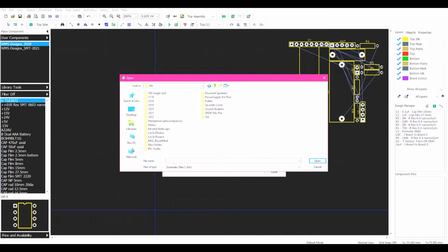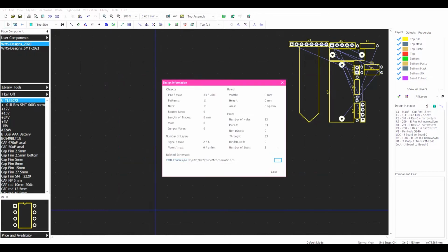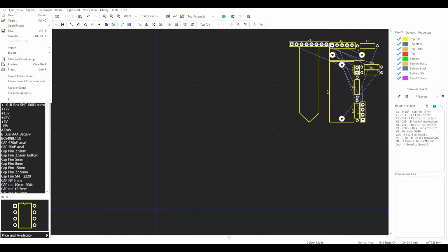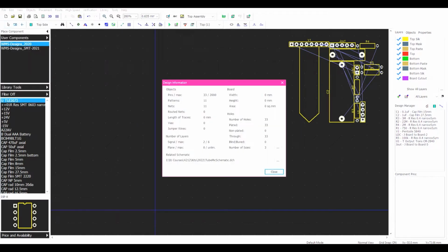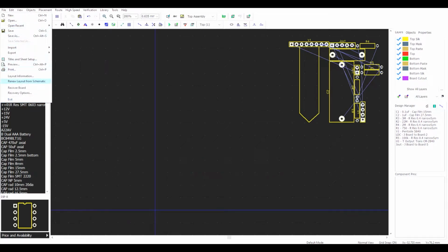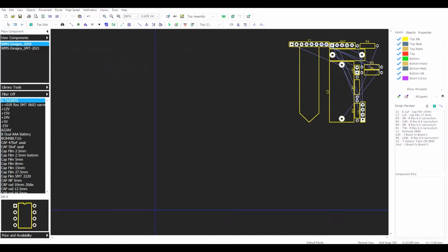Which I thought was right there. There it is. And now it's connected. And then when I update the schematic, I can update the schematic and then come here and tell it to update from that related schematic. Once I know it's there, I can renew it, Control Alt U, and that will take any changes in the schematic and move them over here to the circuit board.